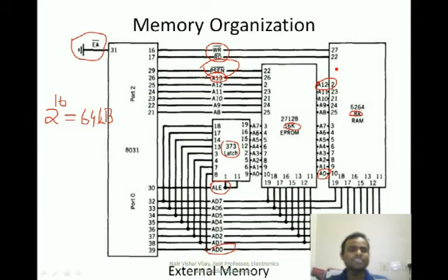So this is how an external memory is interfaced with your 8051 microcontroller. Always remember, first thing, ground the external access pin. Port 0 and port 2 provide you address and data lines. Port 0 provides you multiplexed address-data lines, and port 2 provides you higher order address lines. So connect these address lines to your memory locations according to the capacity of the memory.